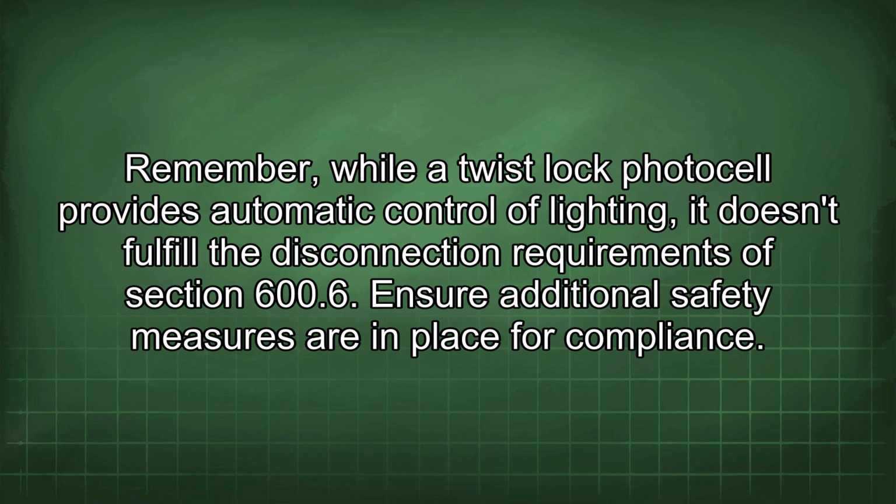Remember, while a twist-lock photocell provides automatic control of lighting, it doesn't fulfill the disconnection requirements of Section 600.6. Ensure additional safety measures are in place for compliance.